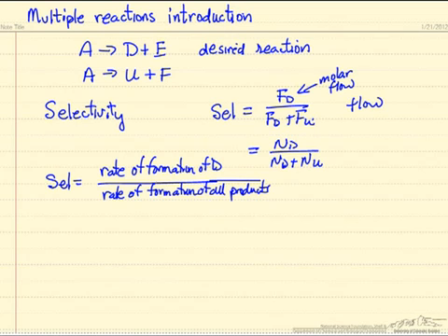having a larger fraction of our reactant go to the product that we want rather than something that's not desirable, something that's a pollutant, something that is worth less than our original reactant. And selectivity is affected by concentration of reactants, by temperature, and by which catalyst is used for the reaction, and catalysts change selectivity significantly.